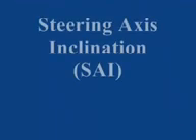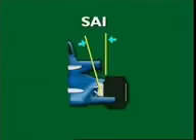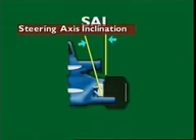Since the offset of the wheel rim determines where the center line of the tyre meets the road surface, it is important that the offset is not changed if wheels are being replaced. Changing the rim offset changes the scrub radius, and also the predictability of the vehicle handling if brakes should fail.